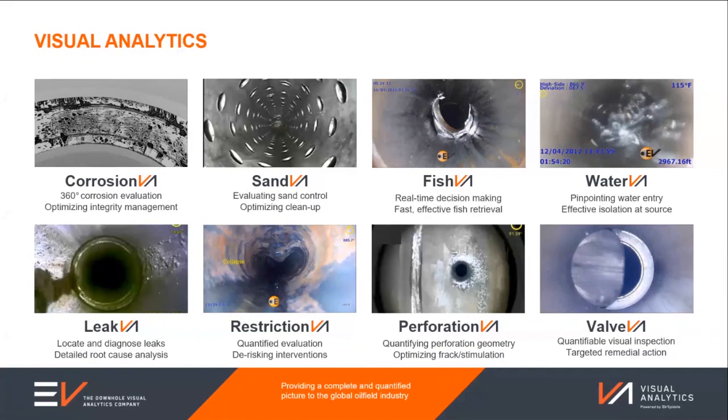The other adaptation that we can do on this, and again, it's particularly relevant for North America, where they'll do what they call air drilling in vertical wells, we actually adapted the camera to have a series of ultraviolet emitting light sources. The great thing about that is that as you run down with the camera through the open hole, any of the formations that have hydrocarbon present physically start to glow under the effects of the ultraviolet. So you're coming down through the rock and just seeing black or dark different materials, and then you may hit a shale or a sandstone that has the presence of hydrocarbon, and it starts glowing vividly in front of your eyes. So that information, along with any open hole surveys or previous geological information, can really help you identify exactly the hydrocarbon bearing zones and potentially tailor the final completion design and production strategy there.